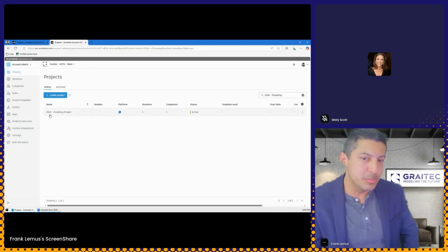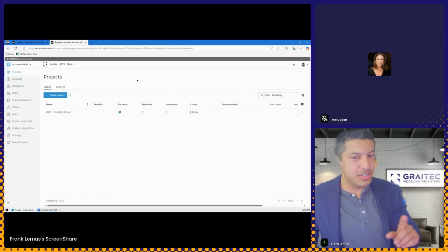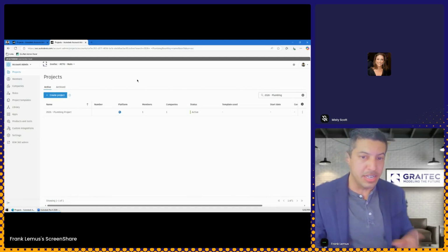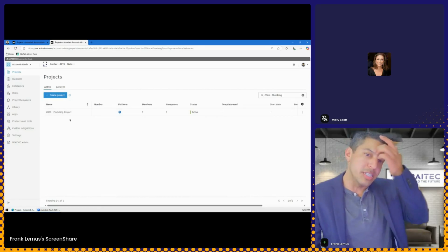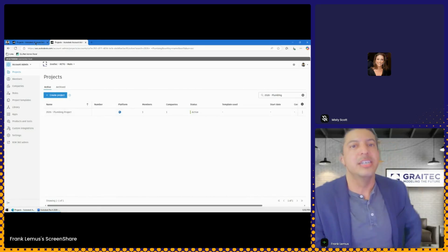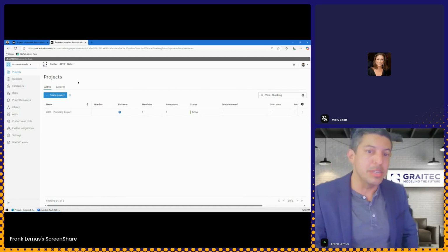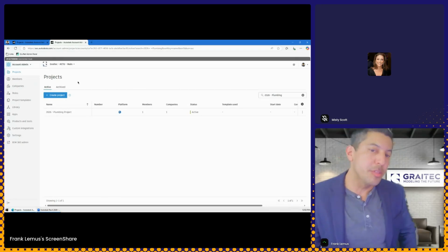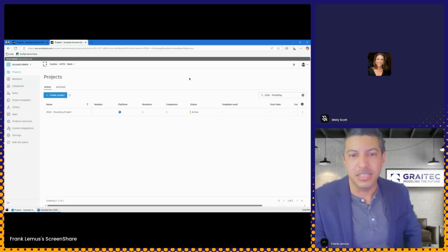But one thing I do want to mention in terms of versions, if we're talking about Revit, is that even though the bridge allows you to connect different projects, even of different projects with different versions of Revit inside of each project, the same limitations will apply. So if I had a 2026 project and I had a 2024 project, I can bridge them together and I can even transfer files, the RVT files or the PDF files and all of that. But whenever Revit tries to open any of these files or link them in, they will have the same limitations as you are already familiar with from a Revit standpoint. From an AutoCAD perspective, it's going to work just the same as it's always worked.